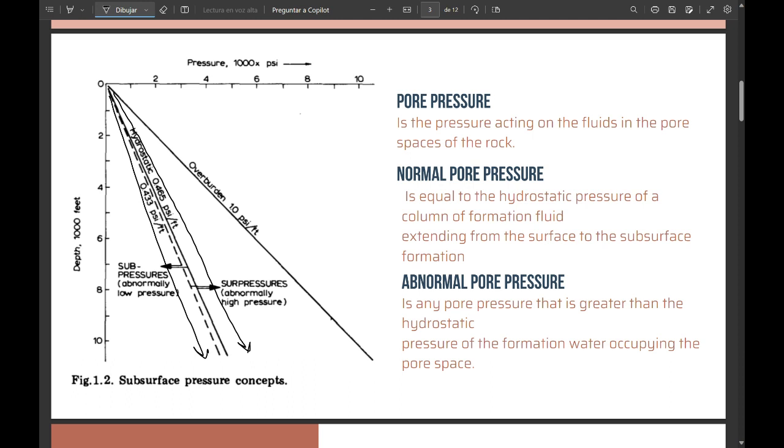For this condition, we can see that it implicates the wellbore stability, the drilling safety, and the hydrocarbon reservoir behavior. This excess of pressure is the reason why surface control equipment, like BOPs, are required when drilling oil or gas wells. Also, this abnormally high pressure can occur at any depth, ranging from only a few hundred feet to great depths. The cause of the abnormally high pressure is attributed to a combination of various geological, chemical, geothermal, and mechanical changes.